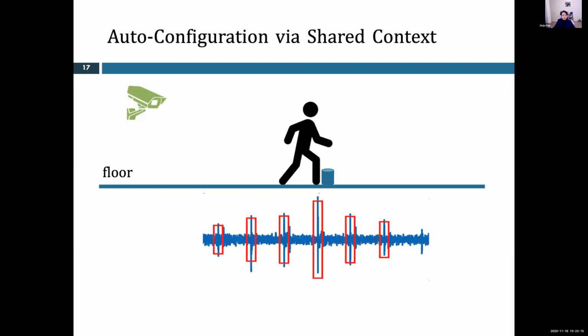So when a person walks by a sensor, their first step induces a signal, which is circled in the red box. You can see it increases when the person approaches, and decreases when the person leaves. This increase and decrease pattern can be profiled to localize the footstep, the relative location of the footstep to the vibration sensor on a one-dimensional path.